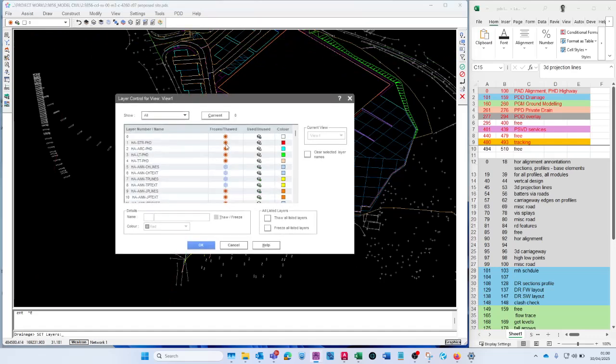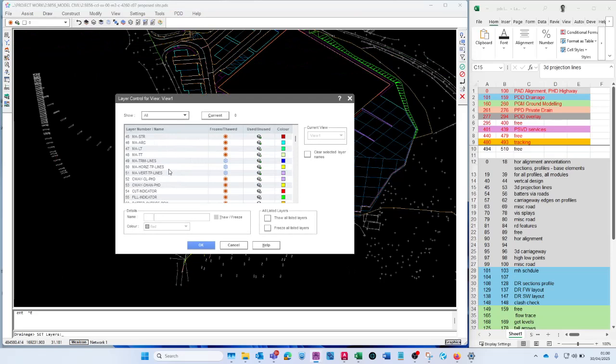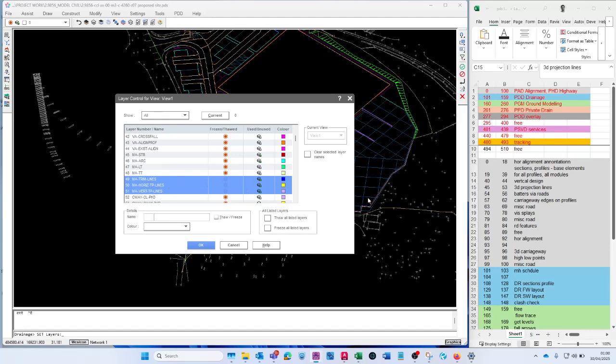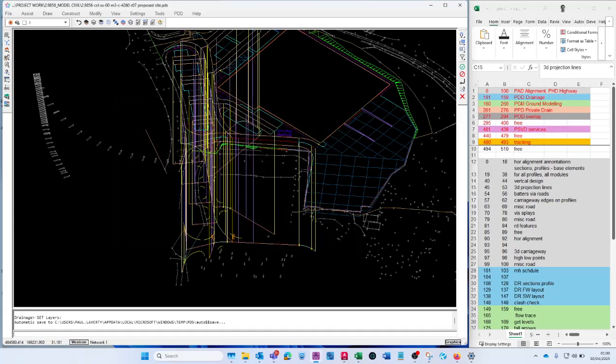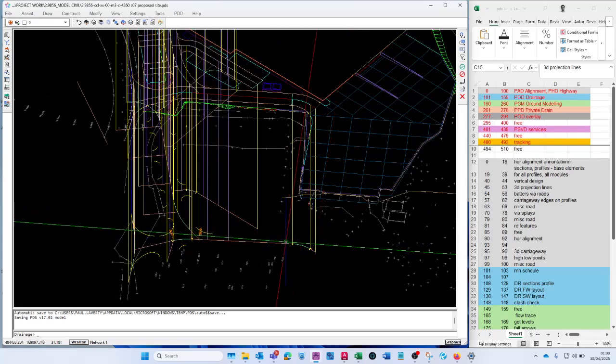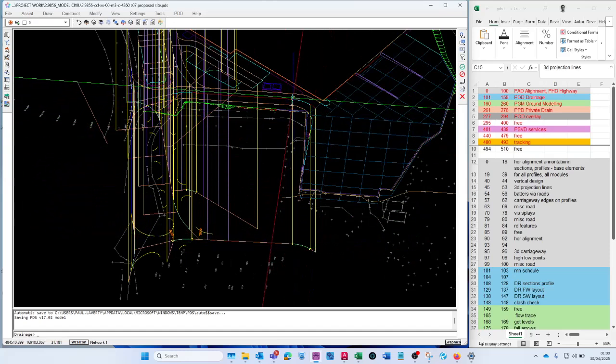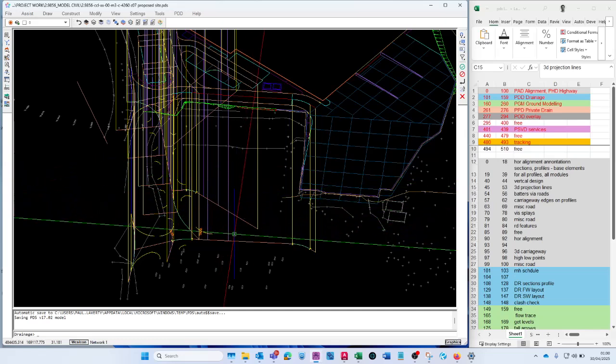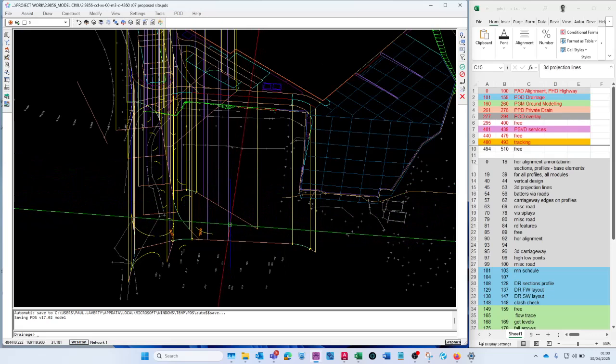So let's turn the layers back on. Master, which is 49, 50, 51. So in that little group, we turn them on. There. So here's the start of the curve in 2D. There, you go all the way up. That's the start of the curve in 3D. End of the curve in 2D, go all the way up. End of the curve in 3D there. End points of the road. And then you have, in this case, lavender, which is the change in vertical gradient.